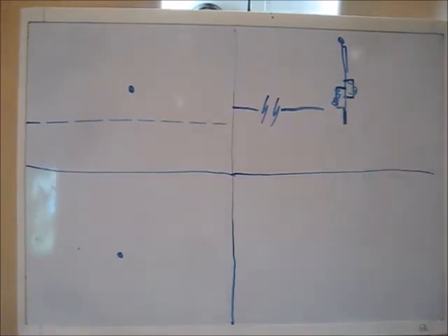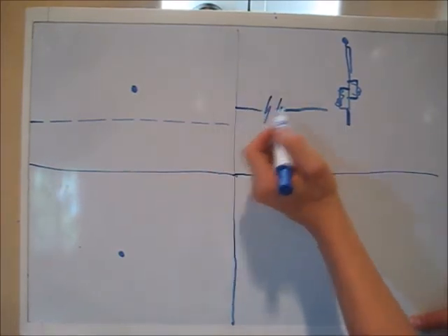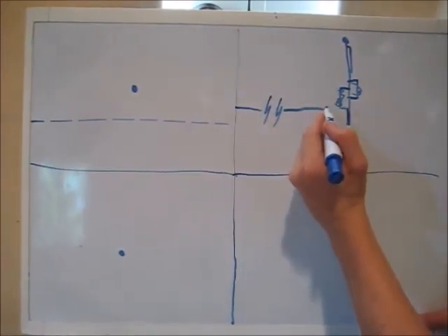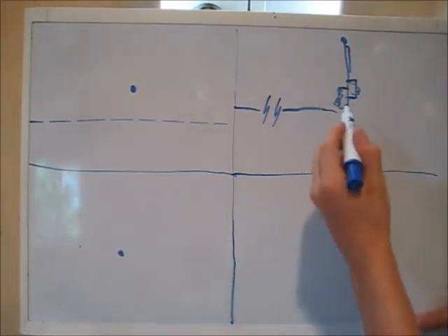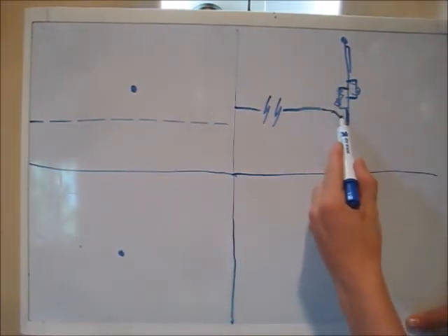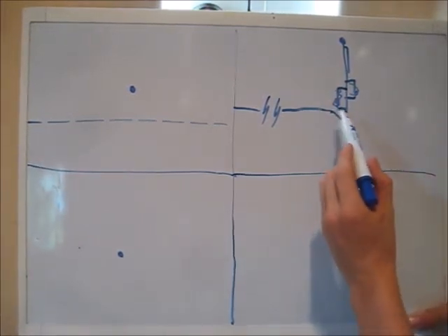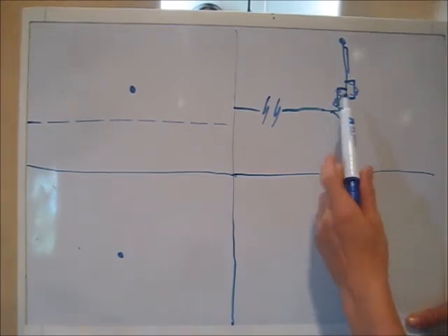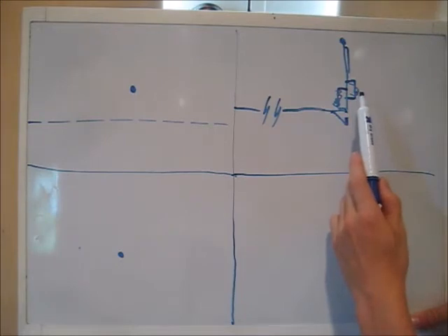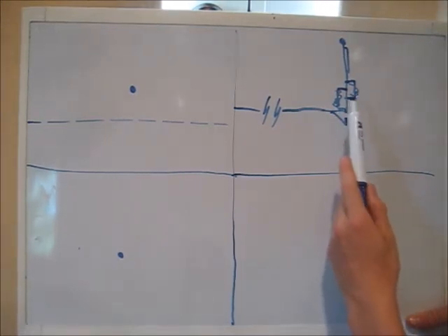So, the standard formula for a vertical is you have your coax coming in, and your coax comes into the feed point. I mentioned the center conductor and the outer shield of coax earlier. The outer shield runs to this part of the antenna, which will usually be isolated from this part, and then the center conductor runs to this part. So these swirly things are representing traps, which a lot of verticals have on different spots. They just make the SWR lower on different bands.